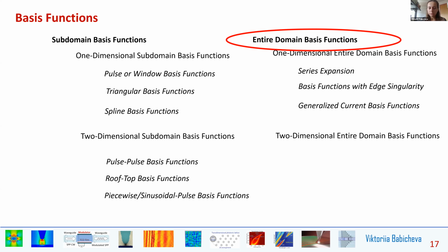The fast varying distribution may also be determined using subdomain basis functions. And a model for later use is a single-term entire-domain function, for the case of charge and current distribution on a strip or slot.